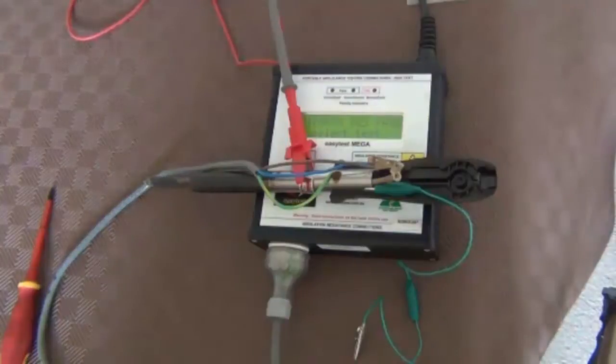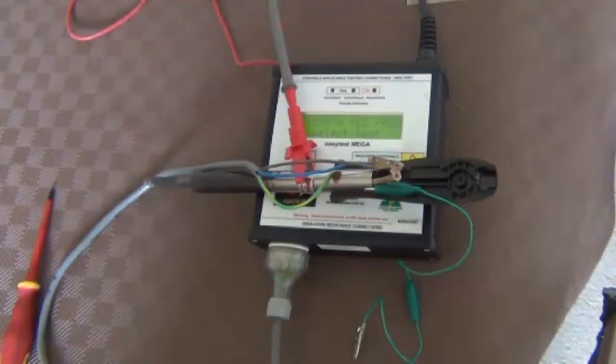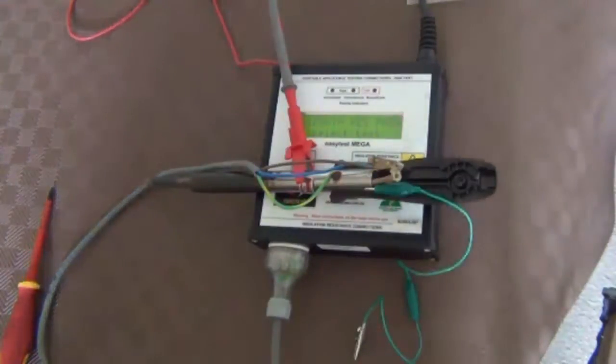Right, the next one we'll look at is the insulation resistance test, sometimes called a static test. The insulation resistance test differs from the run test or the earth leakage test in that it is a stress test. We put 500 volts between the active, neutral and earth. We join the active and neutral together and put 500 volts to earth and try and blow a hole in any weak point. So let's see how it works.